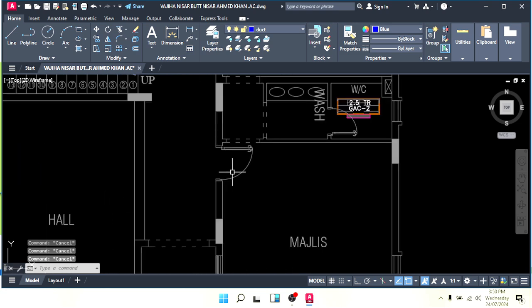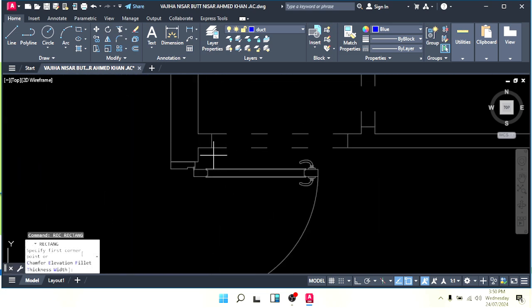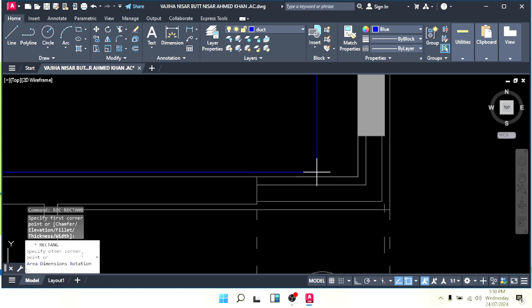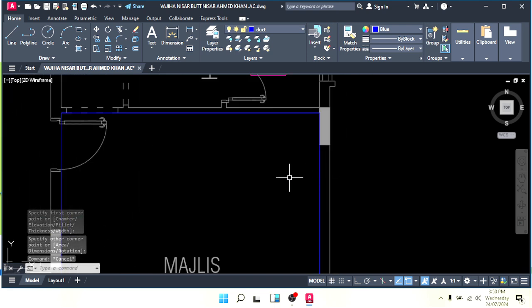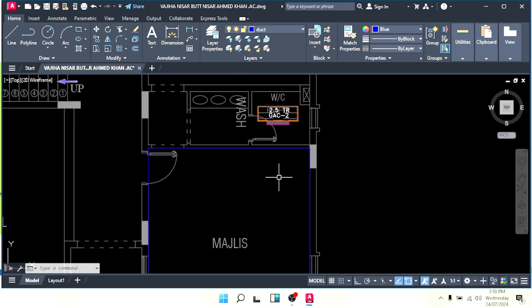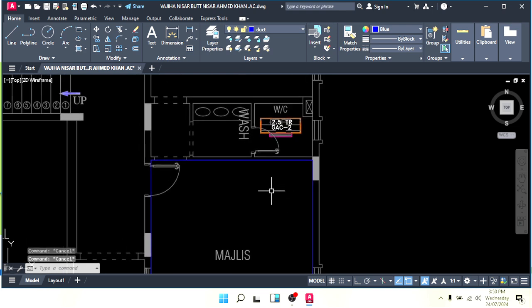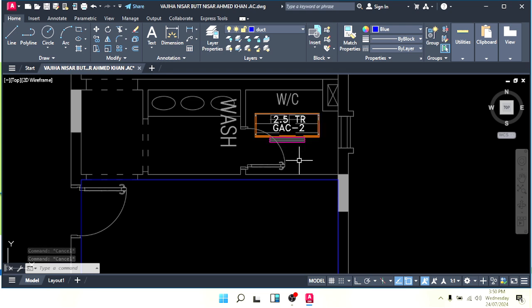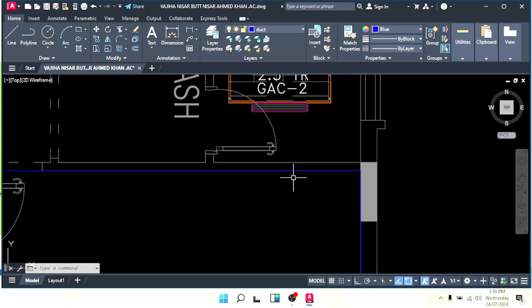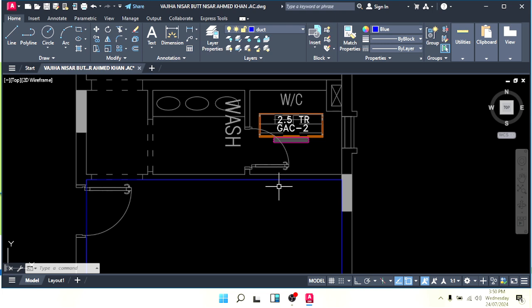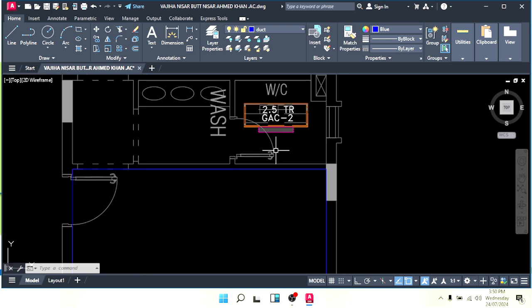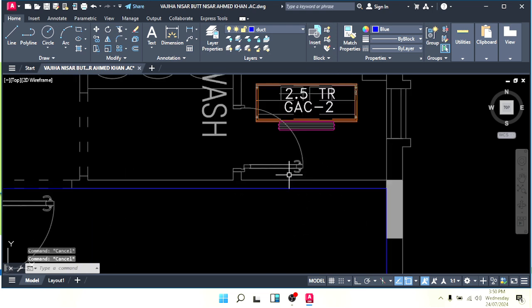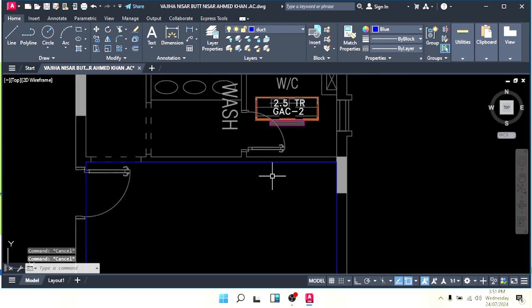So let's get started. First of all we have to make the bulkhead in the ceiling. We have to decide the width of the bulkhead, I mean the distance from the wall to the bulkhead, because we have a duct size that has to pass here. The ceiling companies don't know the requirement of the duct, they don't know what size of duct will pass through here, so they cannot decide the bulkhead. So we have to give our minimum requirement, and they have to follow that.